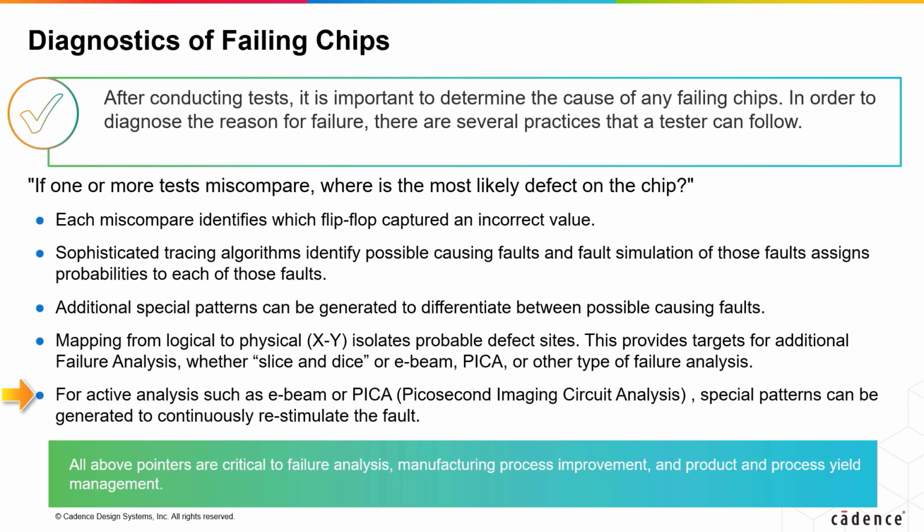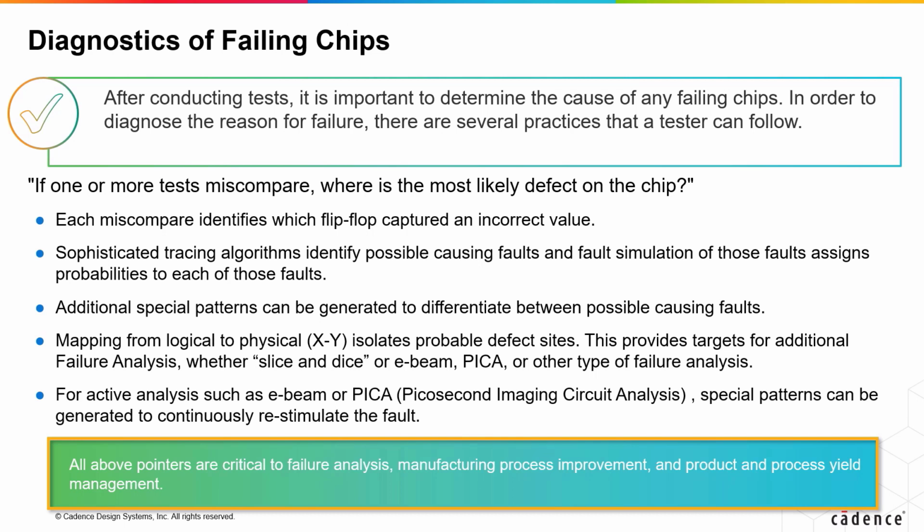It can be very valuable to monitor the types of defect that are occurring. This can identify weaknesses in the design of the technology cells and acts as the ultimate monitor of the technology process and manufacturing line. If the defects are dominated by one type of defect, for instance, it is probable that the process can be adjusted to eliminate most of that defect. This is how the yield of a technology process is improved over time, holding down the cost of chips and enabling Moore's law, as well as helping us sort out good chips versus bad chips.